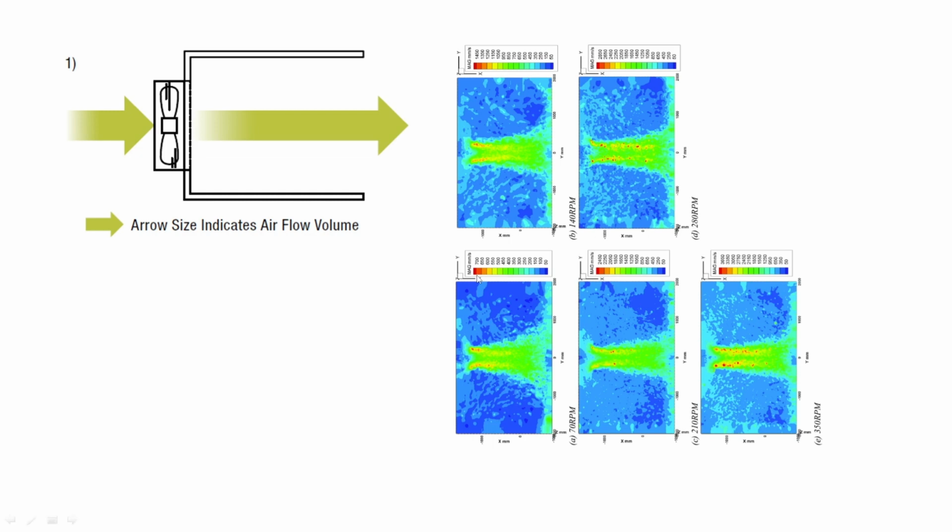So the CFM test that I'm referring to, CFM is just a volumetric flow rate. You can convert meters per second into CFM by knowing the surface area of the object you want to measure, because you can see the surface area of the tube, so pi r squared, and CFM is just cubic feet per minute. So let's put that in feet, and then the airspeed, let's put that in feet per minute, so feet cubed per minute, so cubic feet per minute. Short math, okay? So the way it's done for many reviewers for case airflow just is incorrect.